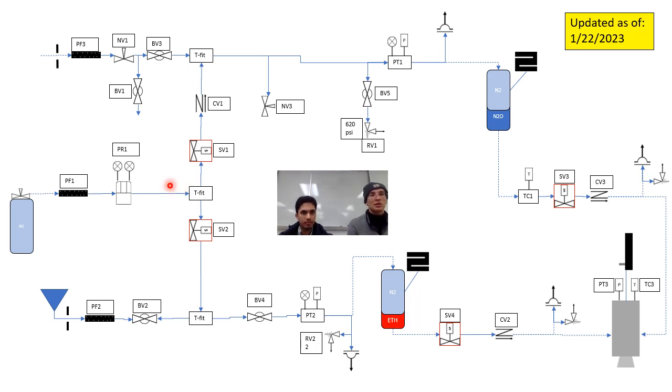So if we're at 0 PSIG, we're actually at atmospheric pressure. At 15 PSIG, which is what we'll be at soon, we're going to be 15 PSI above atmosphere. For your reference, atmosphere is 14.7 PSI, so just about that amount. So we'll be at 2 absolute atmospheres. And if there's a hole anywhere in that feed system, you'll have the force of that pressure being forced out of that hole, which is how we're going to be purging.